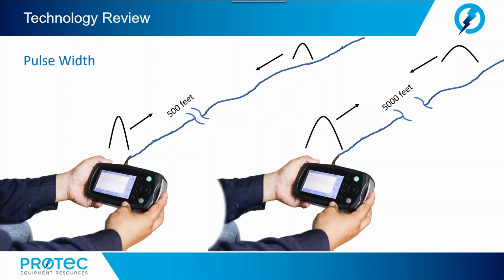TDRs have varying pulse width settings, and modern units, while allowing the operator to vary the pulse width, will automatically set the proper pulse width to the best display for the first event. The larger the pulse width, the more energy, and therefore the farther the signal will travel on a given cable. A TDR's distance range is determined by how far the transmitted pulse will travel while still having a detectable reflection return to the TDR.